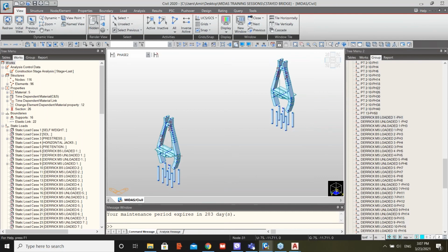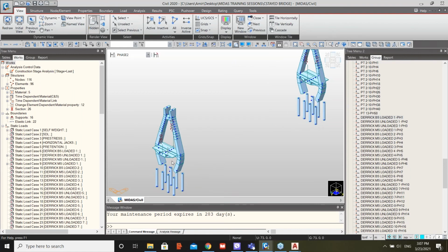And then you see the switch of the derrick, because there are 2 derricks here, one having a larger load and the other having a smaller load. The reason for this is that now we installed this first segment here, so we switched to the other side. This means that this derrick is loading a segment here from the barge and coming all the way up to be erected, while this derrick is staying empty on the bridge because it's not carrying a segment. That's why you can see the difference in the load, but still the weight needs to be included because the derrick is still on the bridge.